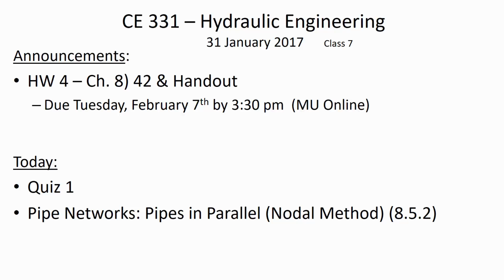Yes? So you're asking about the non-circular conduits? Can you say your question again? So the other form of the Reynolds number? It's just depending on whether you know the kinematic viscosity of the water or the absolute viscosity of the water and the density. Yeah, because remember that the kinematic viscosity of water is the absolute viscosity of water divided by the density of water. So they're essentially interchangeable.